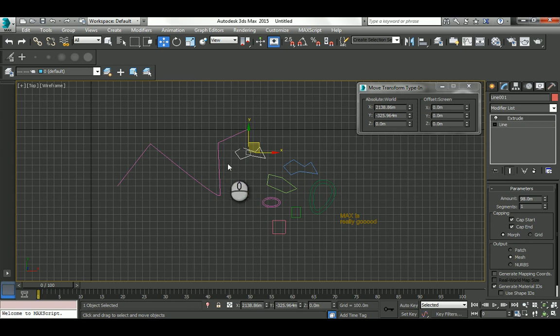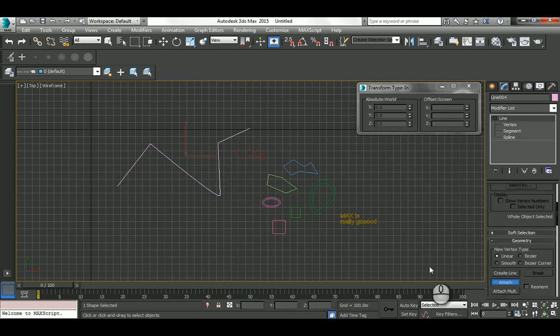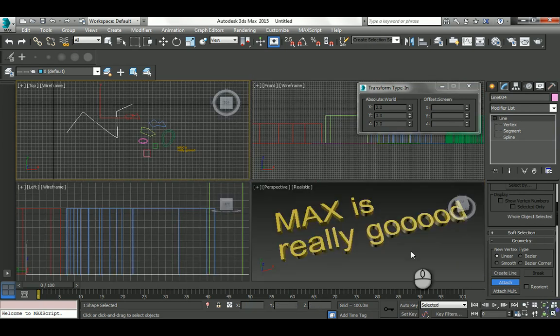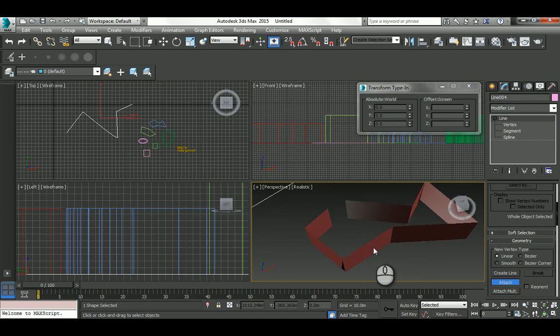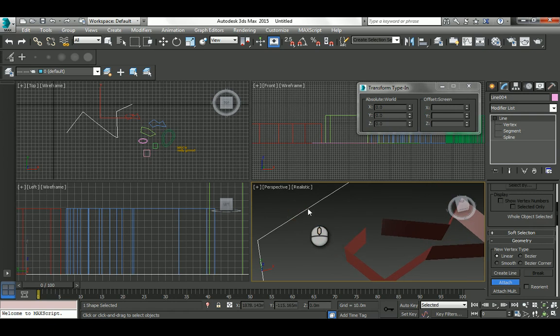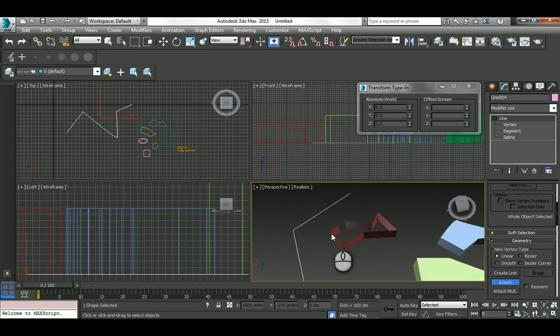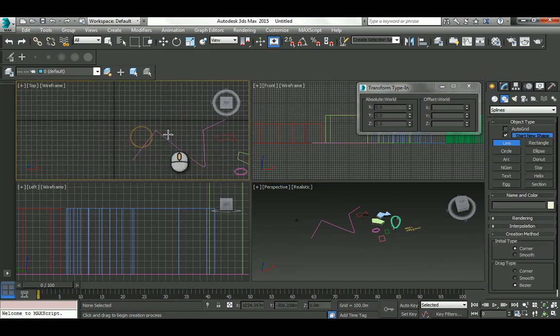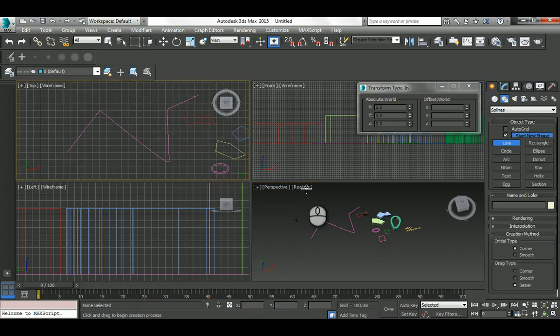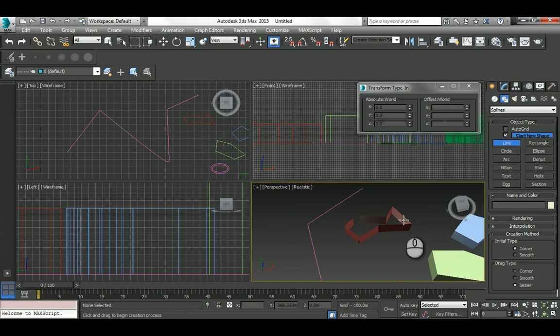See this guy, and when you hit attach, it isn't working with this 2D line because this is not a 2D line anymore. It's been changed into 3D. See, that's why I scared the hell out of myself now, because it's not a 2D object now. So Max is preventing me from attaching this guy to this guy. This is a 3D object now, and you're not allowed to do that. So okay, really freaked out. So let's draw another 2D line, because here in the top view it looked like just a 2D, while in reality you're just having a top view of this 3D object.